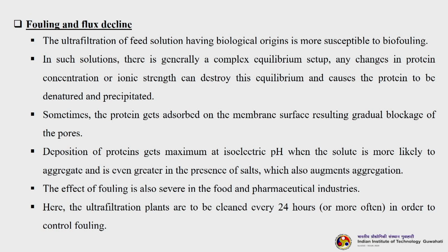The ultrafiltration of feed solutions having biological origins is more susceptible to biofouling. In such solutions, there is generally a complex equilibrium set up. Any changes in protein concentration or ionic strength can destroy this equilibrium and cause the protein to be denatured and precipitated. Sometimes the protein gets adsorbed on the membrane surface, resulting in gradual blockage of the pores. Deposition of proteins is maximum at the isoelectric point.